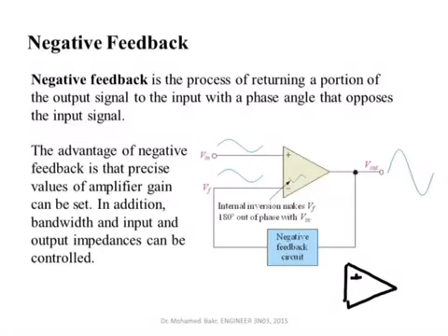For example, if we ground the negative side, and this is the output, then if you have a signal here which is, say, 0.1 volts, because of its high gain, this 0.1 volts will result in the output saturating, reaching the maximum possible output voltage, which is VCC, the positive supply voltage. So you are not able to amplify this signal, say, by a factor of 4 or 5.